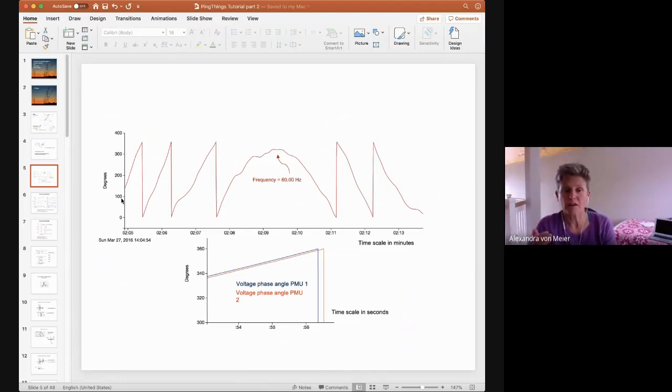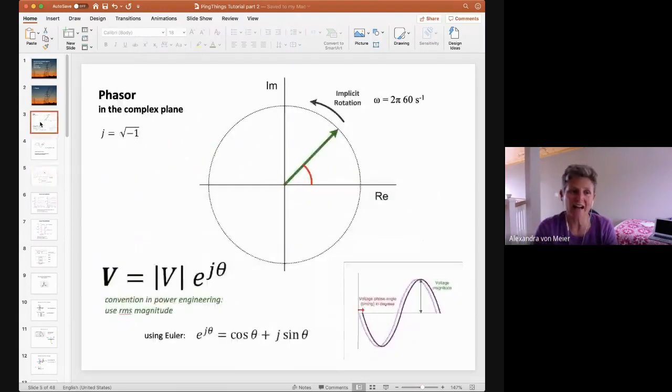So the upper part of the graph is when you are looking at a single channel of measurement against the clock, and it will show basically the phasor wrapping around, because the way the PMU is configured is that if the frequency is exactly at 60 cycles, your green arrow is going to appear stationary, so that angle would stay constant. But given that, everything is computed on the basis of an exactly 60.00 hertz frequency.